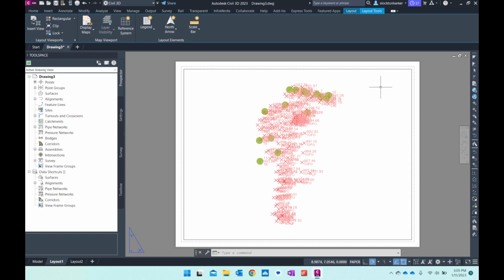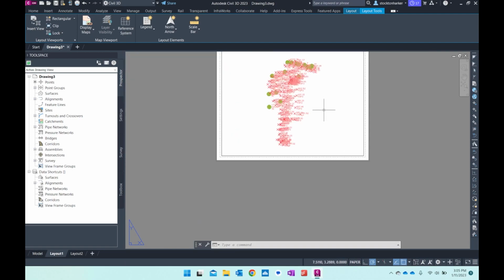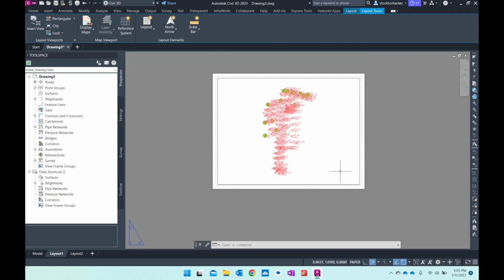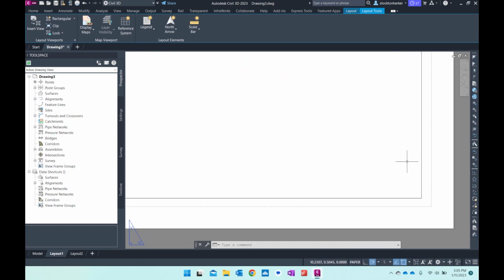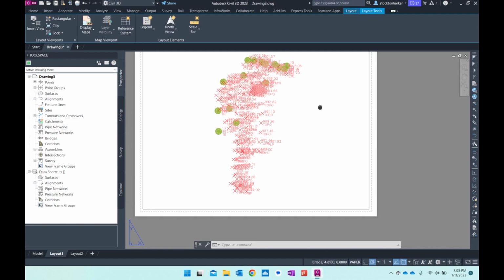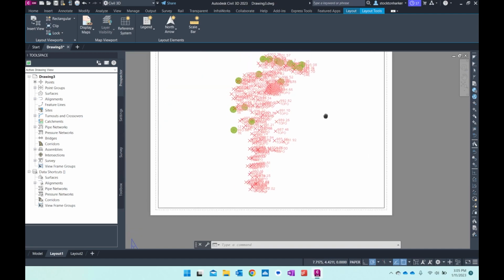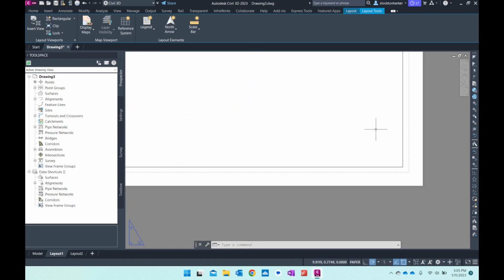The next thing that we want to do is create a simple title block. If you've ever seen civil drawings or even regular construction drawings, there's a title block that says what's going on in this drawing. What are we showing you exactly? In this case, we're just going to do something really simple. We're just going to draw a rectangle in the bottom corner of this paper. So I'm going to zoom in over here, and some of these commands that I've been using, if I press and hold the scroll wheel of my mouse, it allows me to pan, to drag around the model, or in this case the paper. And that's one thing I've been doing to get over here, and then I'm using the scroll wheel on my mouse to zoom in and out.